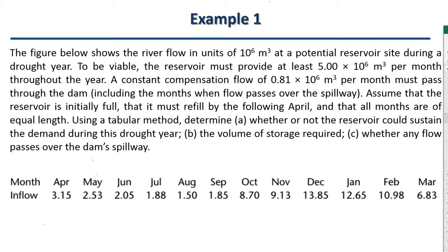If you are looking at the control of the flood through the spillway and want to see if the flood control has the capacity or not, you need to look at the wettest year, or the wet year. You are not supposed to look at the flood through the drought years or the dry years. You know why? Because in the dry year you have no problem with the flood. In the dry year you have more concern for the water supply. On the other side, for the flood, you are supposed to look at the wet years, not the dry years. Is that clear?